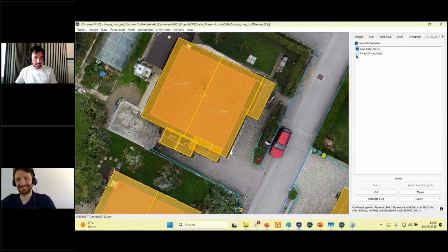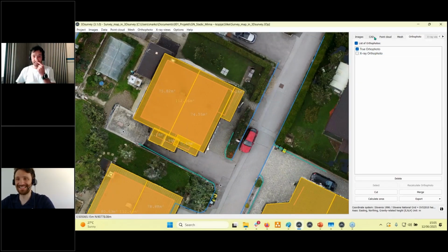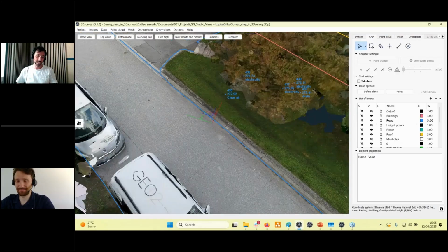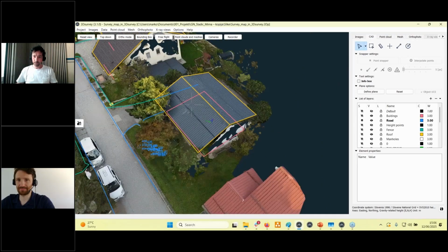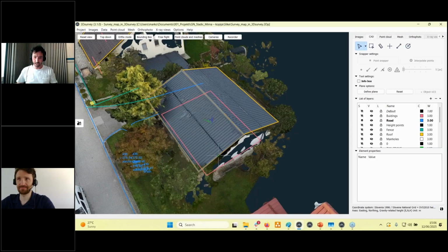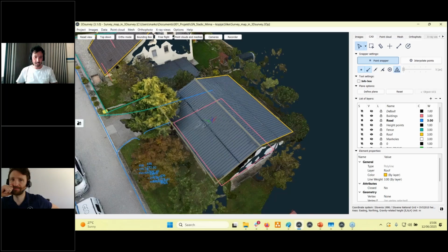Very good question and very tricky for us, yes. So we did it like so: if the polygon is closed in the CAD, so let's take one roof, for example, this here. If I go to the select tool, select my polygon, and if I see the attribute closed, it's going to be filled with color. If I set no, it's no longer closed, but I lose the last connection here.